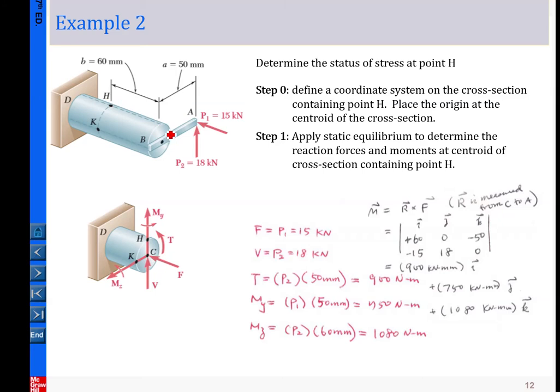So here, this is a circular shaft, and this is a cross section which is circular. That's the cross section here. Then we define the coordinate system, and say this is the centroid. We define the longitudinal or axial direction as x, and H is on the north pole, so that's y, and K is on the west side, and that is z. So for step one we define the x, y, z coordinate system and place the origin at the centroid.